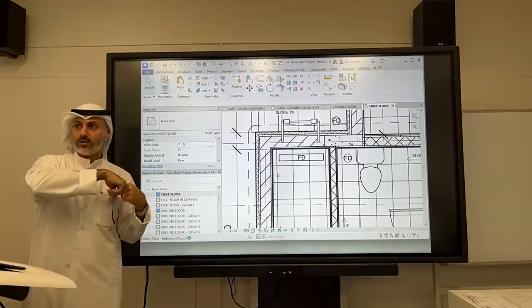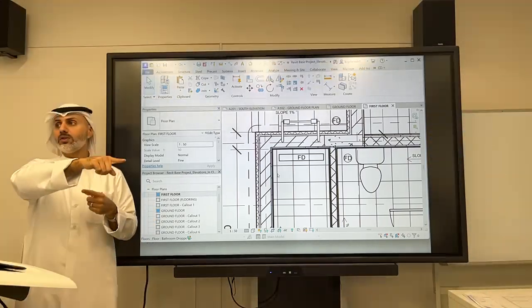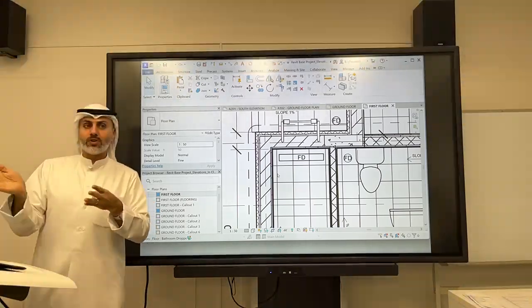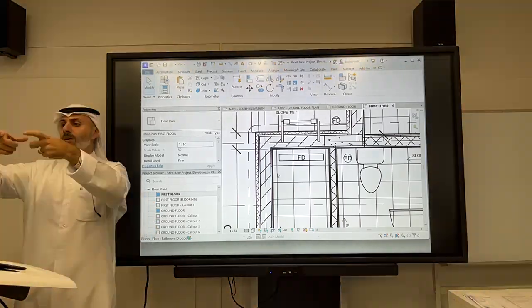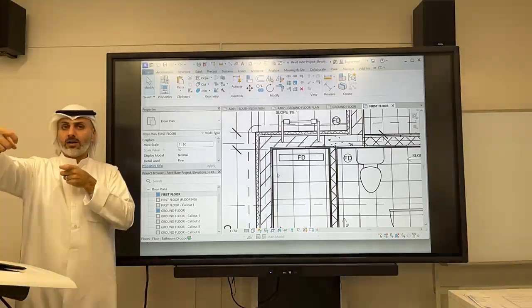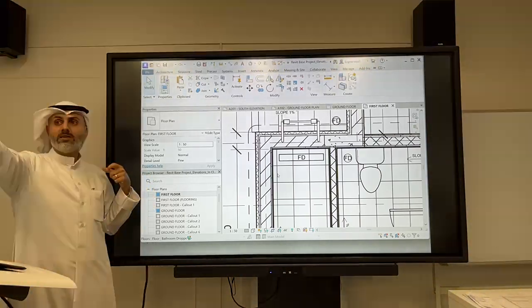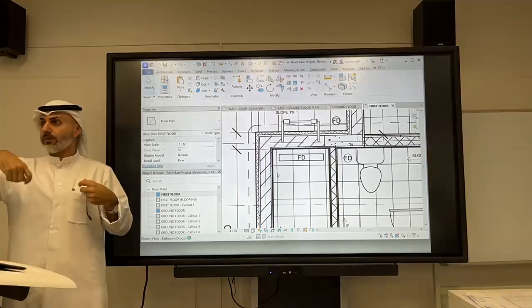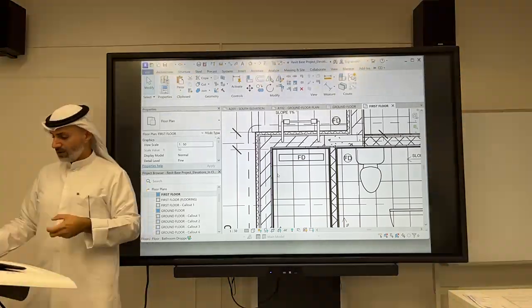So it's your job as a designer to coordinate with a structural engineer, whether you make it part of your design or you tell them to change the design. Because the column carries the load, a square might carry the same load as a rectangle: the square could be 40 by 40, but the rectangle 20 by 80 to carry the same load. So you have to work with the engineer so that you're following the same materials.